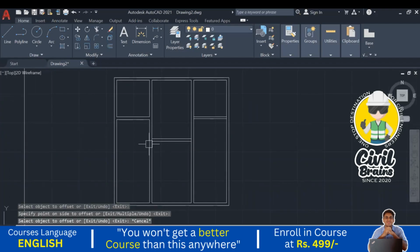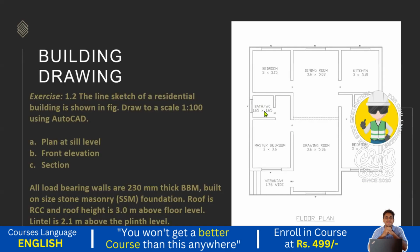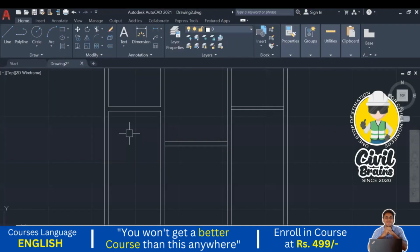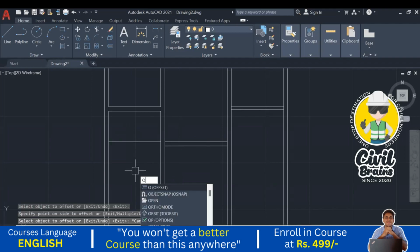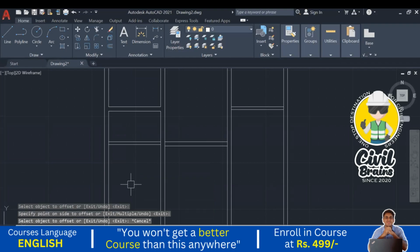Okay, so next again we come to this room. Next here, yes, here it is a bathroom. So what is this bathroom? 1.65 and wall thickness is 0.15. And here there is nothing. So again here 1.73 and the wall thickness is 0.15. Okay, we'll draw that one. Let's go to the offset. We'll go to the offset 1.65. Press enter. Okay, offset 0.15, that is the partition wall. Enter. Clear? Okay.